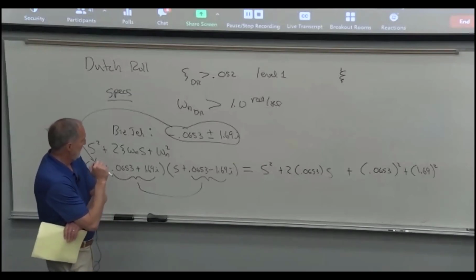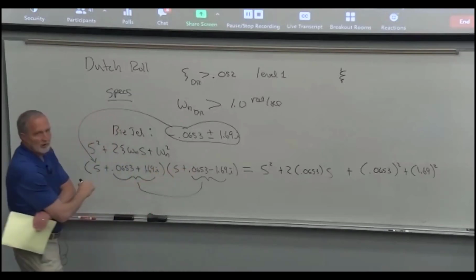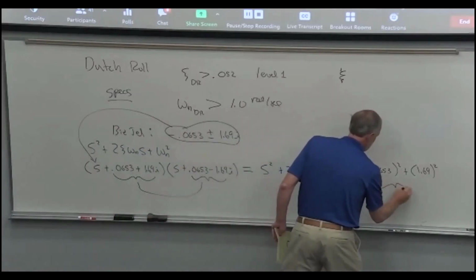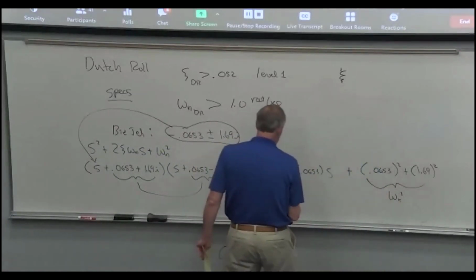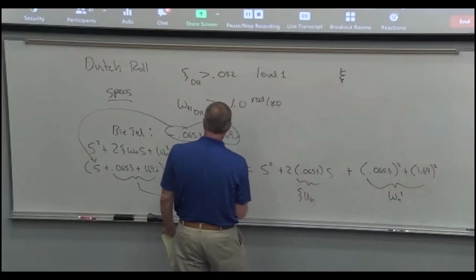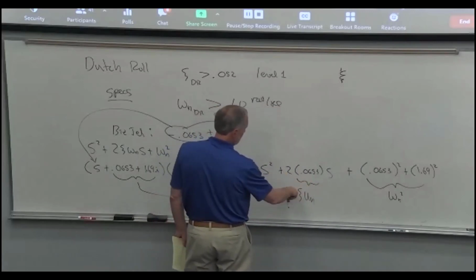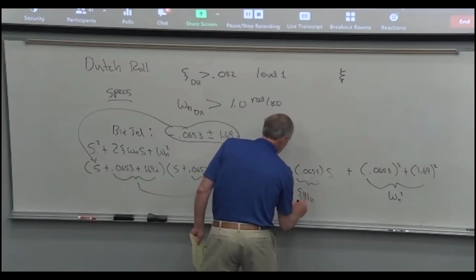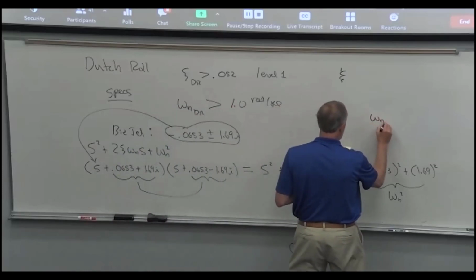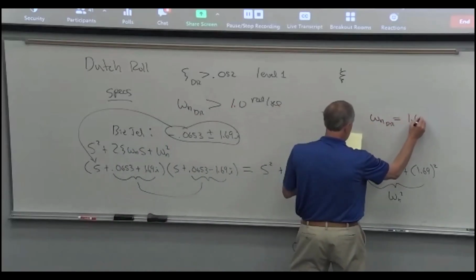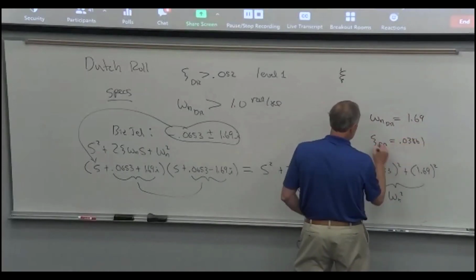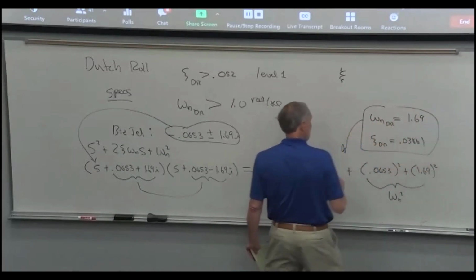Yeah. So you almost have to just do it yourself and multiply it out, that times that times that times that, and then you realize you get this. But this is what gives us the natural frequency squared, and then this is the damping ratio times the natural frequency, because it's 2 times that. And so you can back out the natural frequency and the damping ratio to compare to the specs. And so for this, this is what we get from this thing down here.